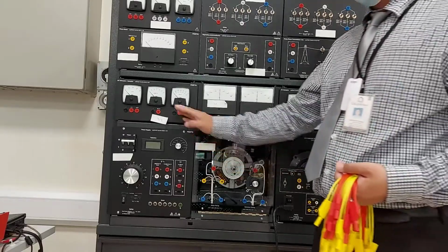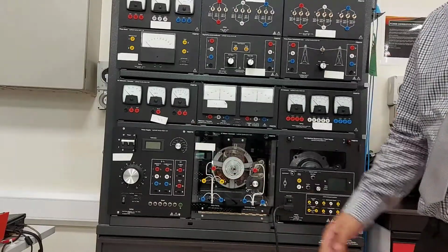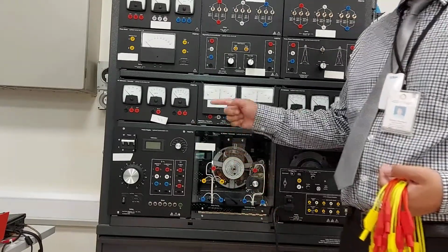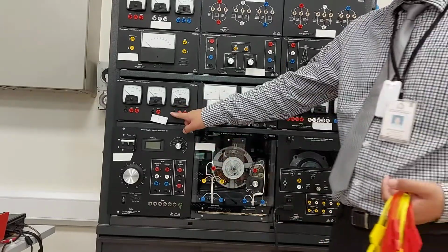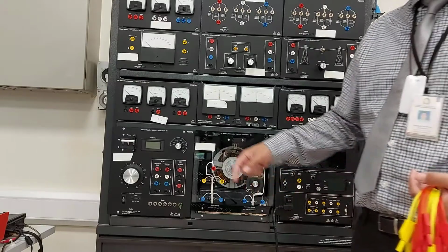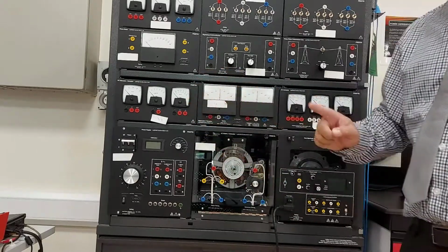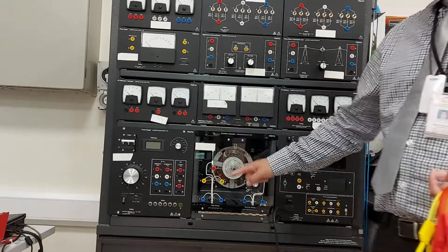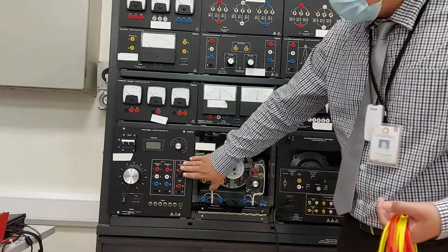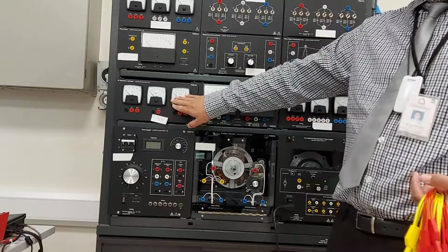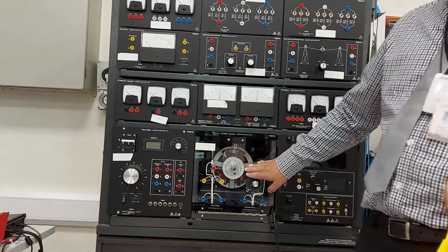We only need 3 modules. Here you will measure the resistance of each motor winding using a voltmeter and ammeter. With this information, you will calculate the power losses for each of the windings. We need the power supply, the DC voltmeter and ammeter, and the DC motor generator.